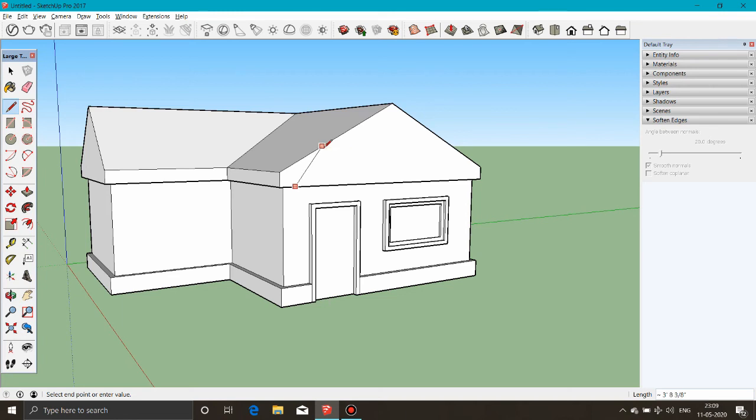Use the Line tool and start drawing a line from this edge. Now hover over the roof edge for a few moments, and as you continue to draw, you'll see a new inference that is purple in color and parallel to the edge we just hovered over. We can easily find out how far to draw this parallel edge by hovering over the ridge point to focus attention there. Then, as we come back to drawing our original line, Sketchup will tell us where these points meet.